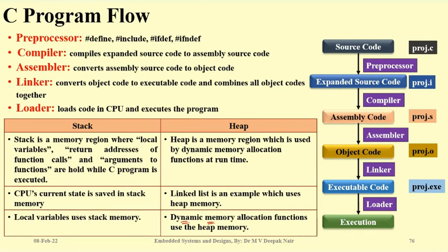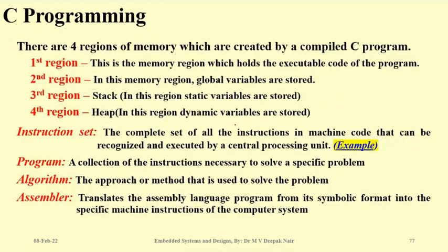But the stack is always fixed. Remember, stack is fixed memory, it cannot be changed, whereas heap is dynamic memory and can change its size. But both of them can be used for managing registers and data which are to be saved during any call or interrupt operations. I will show this part if possible; otherwise, this is a bit too deep for this course.